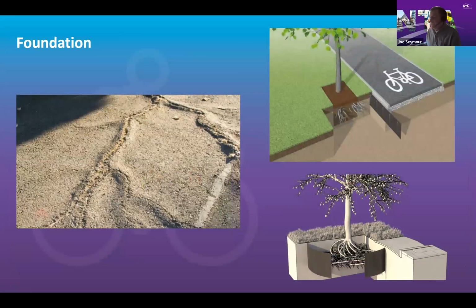Next thing to look at is trees. Just by its nature, we will be running next to trees, or we will be putting in trees afterwards to green the route. But tree roots tend to end up inside pavements if the wrong variety of tree is located next to the cycle track, and we need to consider that.